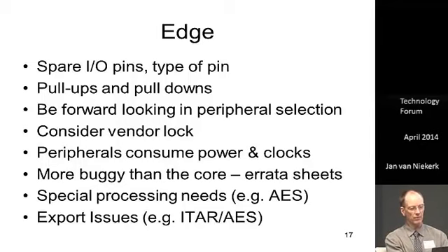The other thing is that peripherals consume power and clocks, so that's important to remember. If you're energy constrained, peripherals that are running actually consume energy. Now the good news is, in the ARM architecture, you can often turn peripherals off when you're not using them.